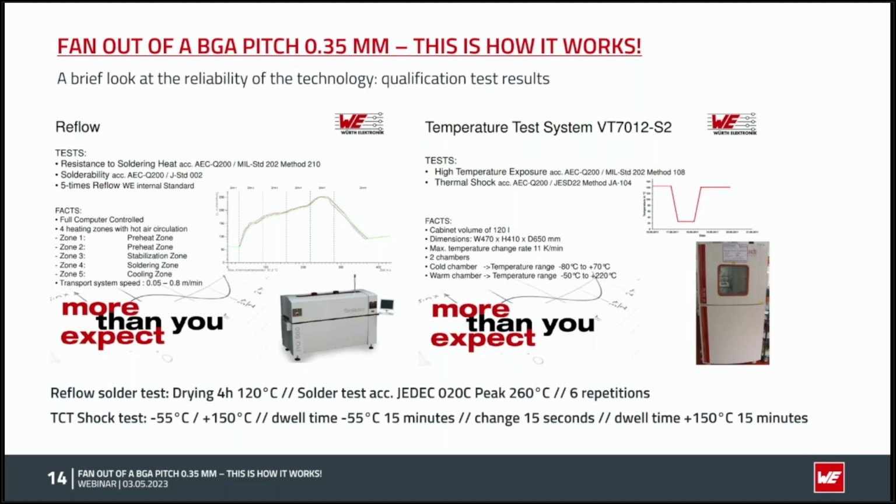And after that, we go into a thermal shock test by minus 55 degrees and up to 150 degrees, up to 500 cycles. We don't see any problems with the connections or other things. So we can say the PCB thickness is very thin, and this is very good for this one.